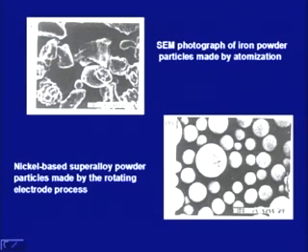Similarly, the shape of the metal powder particles, here we can see the shape is random. So, if we want to calculate the aspect ratio, we will see what is the largest dimension. Suppose this is the largest dimension and this is the smallest dimension. So, we can calculate the L by D ratio for this and we will get a certain value for that. So, we can get the shape of the particle, the size of the particle and the distribution of the size. Sometimes this size may be in larger number, sometimes that size may be in larger number. So, metal powders that we make have three important characteristics. First is the particle size, the second is the distribution of the particle size and the third is the aspect ratio, or we can say the shape of the metal particles.